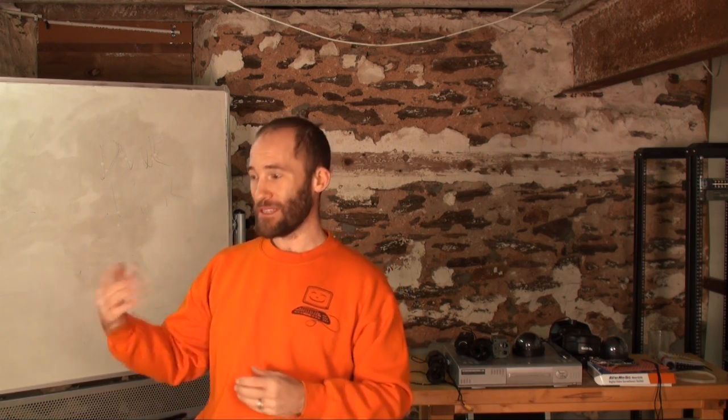Inside-outside cameras, like we talked about, some cameras are built to be inside, some cameras are built to be outside. If you take an inside camera and you put it outside, well, you know what's going to happen. One thing I would say with this is when in doubt, buy outside cameras. So when you're dealing with industrial settings, let's say warehouses, stables, farm areas, barns, that type of thing, although it's technically inside, that's still going to be a pretty harsh environment. So you might as well buy outside cameras just to make sure they're okay.